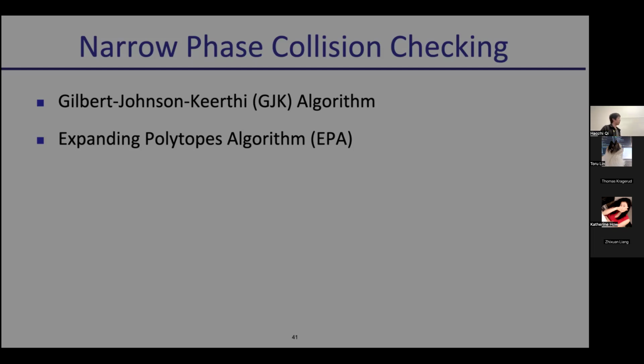So usually that's very sophisticated, and between 2 time steps, you need to consider a lot of things. For example, if there are 2 small objects moving at very fast velocities, if you directly consider the positions in the current time step and the other time step, they may just penetrate each other without you knowing they actually penetrate. And there are a lot of techniques to actually capture those collisions and resolve those collisions.